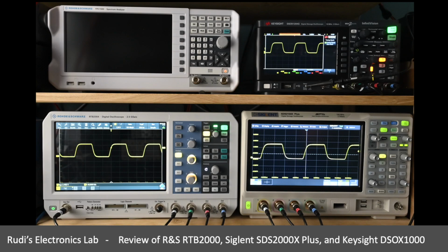Also, in this regard, it's perhaps important that while the other devices talk of a waveform update rate, the Siglent talks sometimes about a waveform update rate and sometimes about what they call the waveform capture rate. But this is seemingly used interchangeably in the specification. It's in the same sentence for the value, so I must assume they mean the same thing by it. Now, looking at the signal, we see the 50 kilohertz signal.